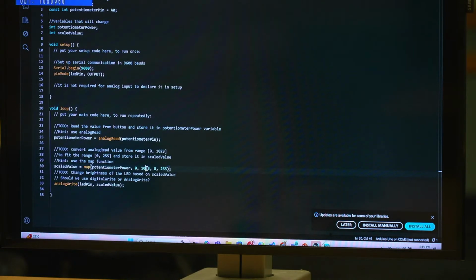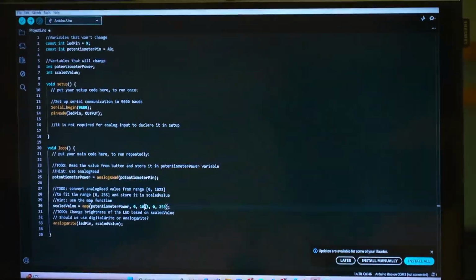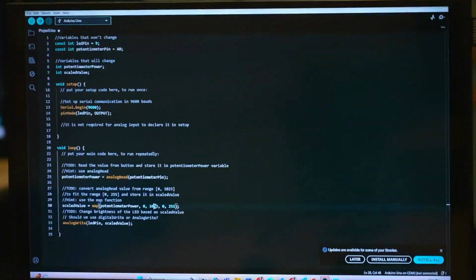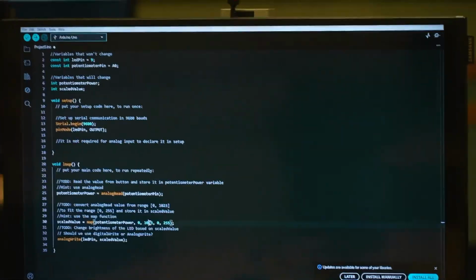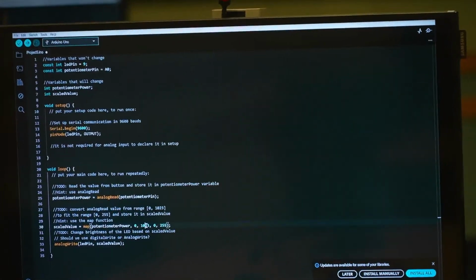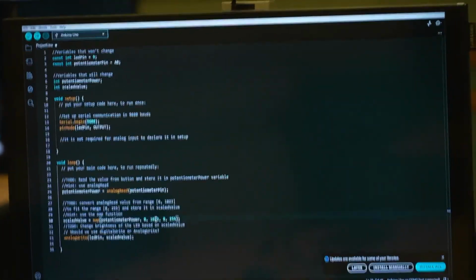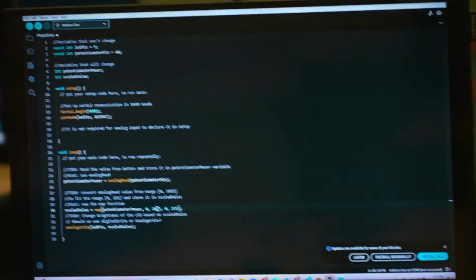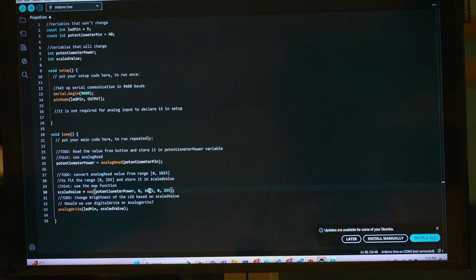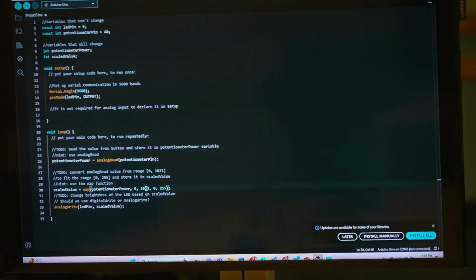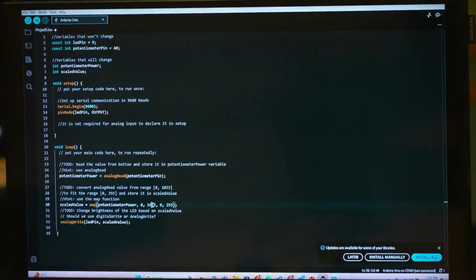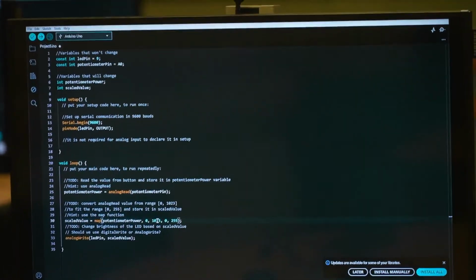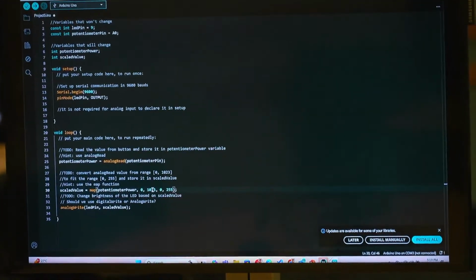Okay. Spin it. Did you check what values it's passing? Like the serial monitor? Open the serial monitor. Oh, that's here. So you can do Serial.println. That's a good way of debugging, to see if the electronics is bad or the software. Serial.println, and just put the scale value.